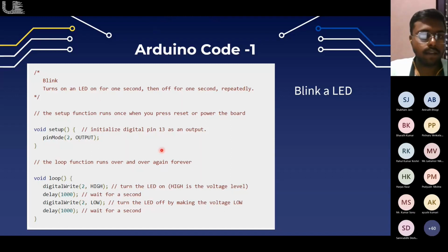To better explain, I can show the board. You can see the pin number 2. So here are the pin numbers. These are not pin number 2. This is pin A0, A1, A2, and they will be called accordingly in the code. They will be referred to as A0, A1, A2. And these are the digital pins, so they will be referred to by their numbers. If it is pin number 3, we will not use the tilde sign there. We will use only 3.